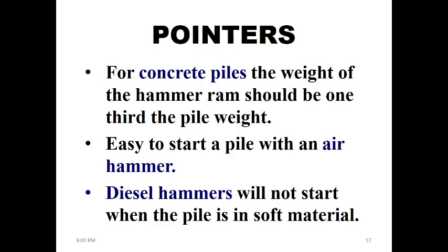It's easy to start the pile with an air hammer, because if you recall how the mechanism works for that compressed air hammer, it's easy to start the process with it. If we have these diesel hammers, it wouldn't start on a soft material, because if you recall its operating mechanism, it's looking for some compression.